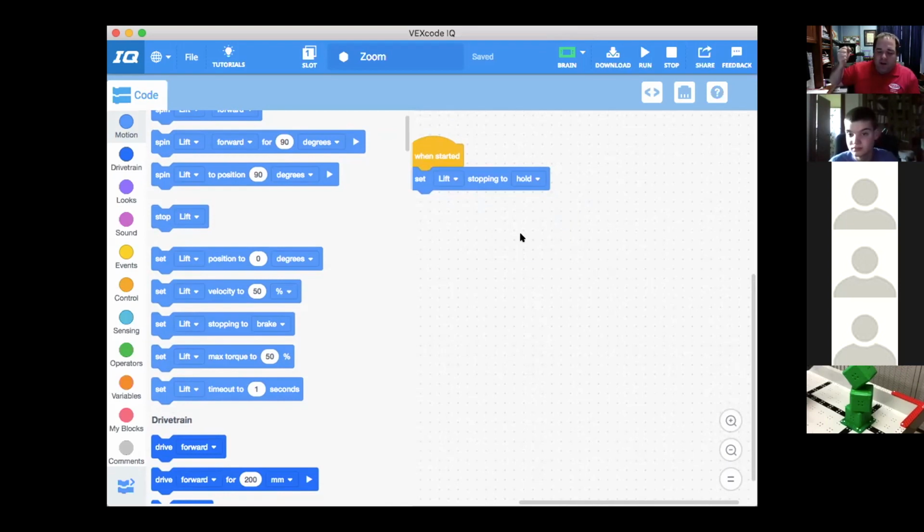It's up to where I want it, and I let go of my button and the arm comes back down. That's because I didn't put a hold in there. When I was done lifting, the arm just drifts back down. I need to put a hold in it, so once it lifts, it stays lifted. When I come down halfway, it stops.